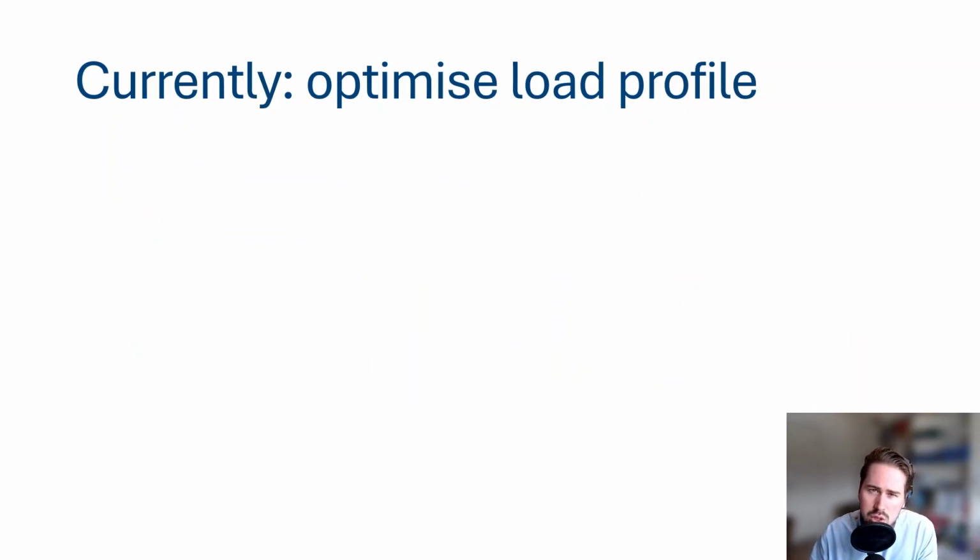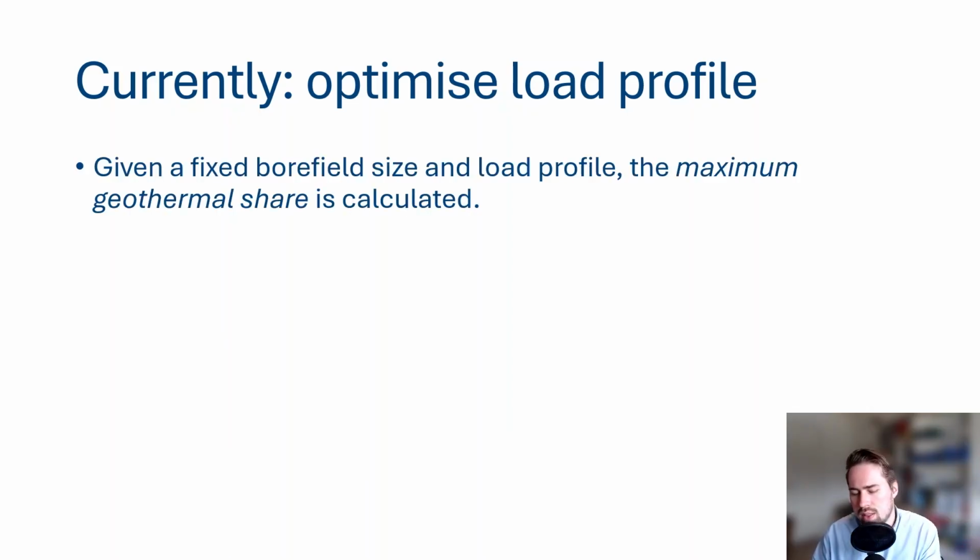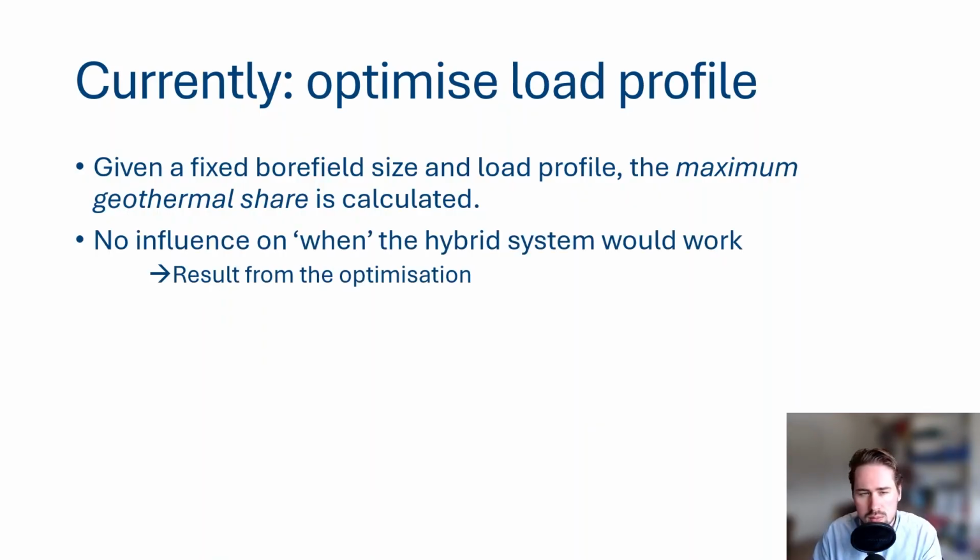Now, just to explain this a little bit more clearly, currently the optimized load profile, what it did is we took a fixed bore field size in the load profile, and then we calculate the maximum geothermal share. And we can do this again either for maximum power, energy, or balance. But you as a user, you do not have any influence on when this hybrid system will work, because that's a result from the optimization.